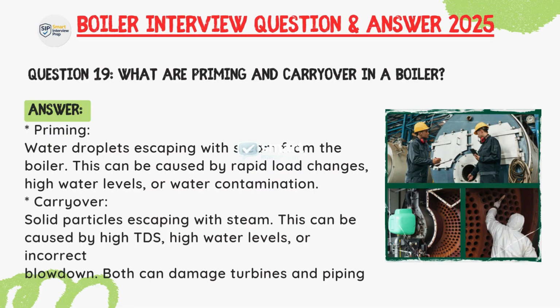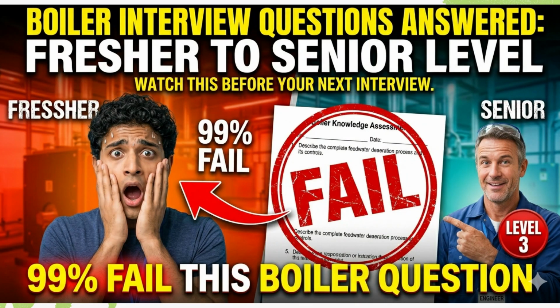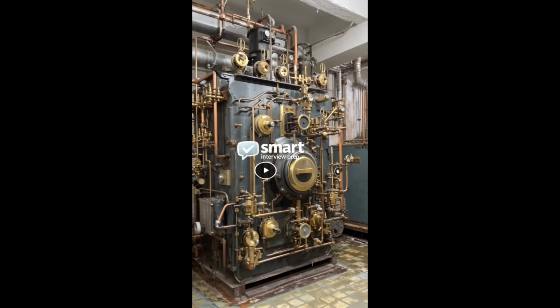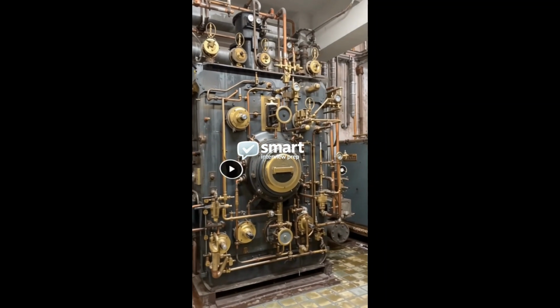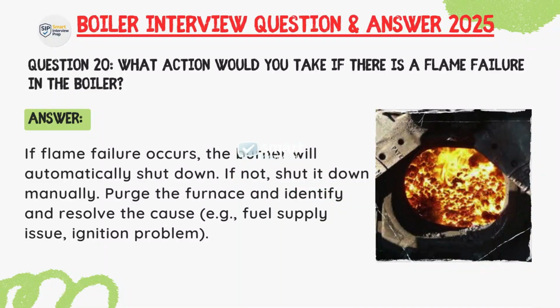Carryover: solid particles escaping with steam. This can be caused by high TDS, high water level, or incorrect blowdown. Both can damage turbine and piping.